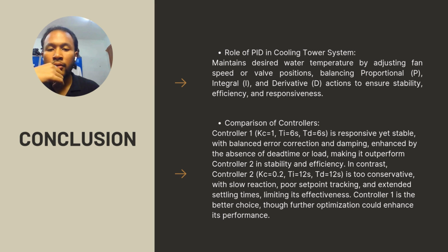The role is to maintain the desired water temperature by adjusting fan speed or valve position, balancing the proportional P, integral I, and derivative D actions to ensure stability, efficiency, and responsiveness for our project.